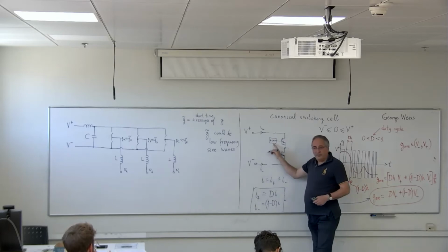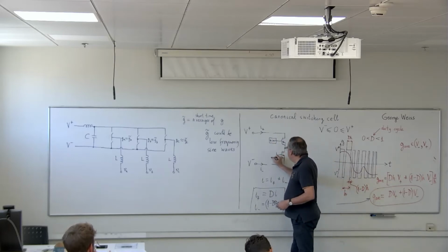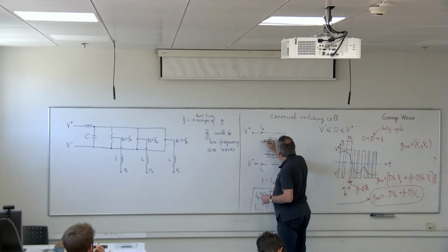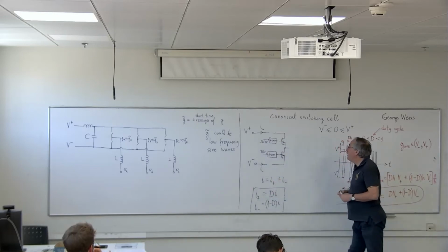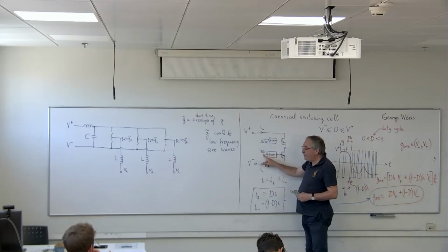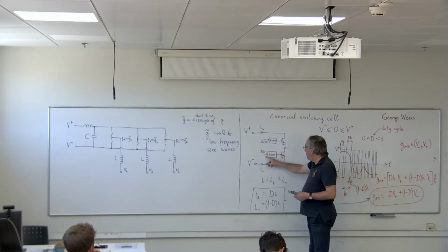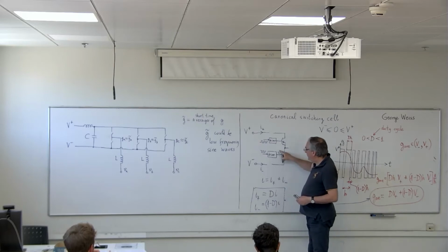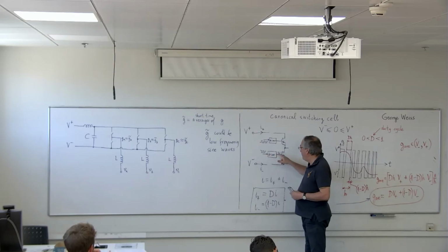Can you read that? Driver. And here is another driver. And the driver has a logical input, so it's a binary input, which is the PWM signal. And when this signal, the input to the driver, is high, it means you want to close the switch. So it will give a high gate voltage. So the gate voltage here depends on the input signal to the driver. When this is high, then also this is high.